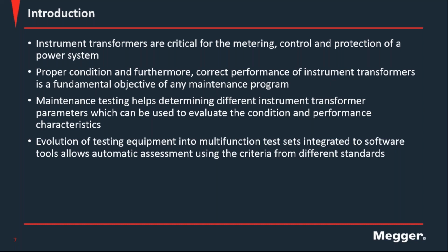Well, this assessment needs, as I was mentioning, results from all the testing, but then it needs some calculations. And these assessments were not common when you tested instrument transformers, because performing that assessment required calculations that were not easy in the field, or you didn't have all the test results because the instrumentation out there was not at the level to get all the results and all the accuracy and be capable of performing everything.